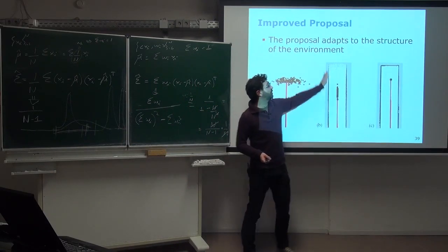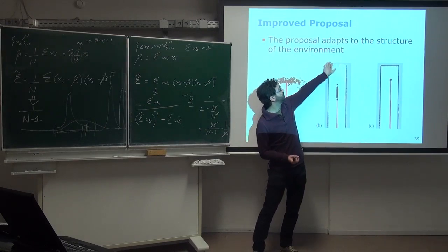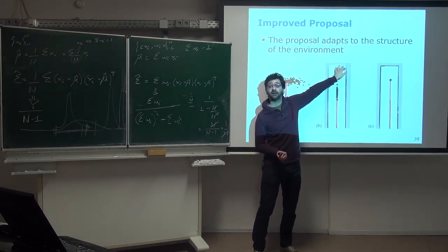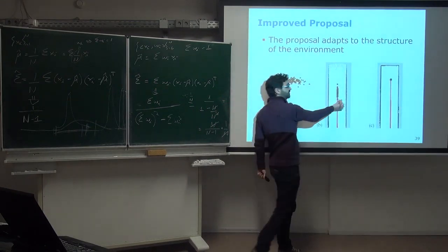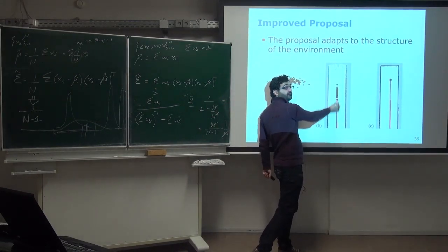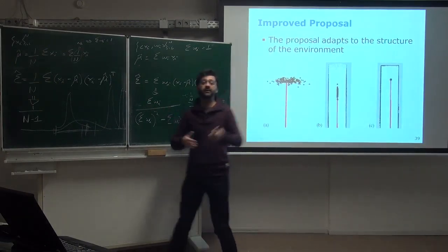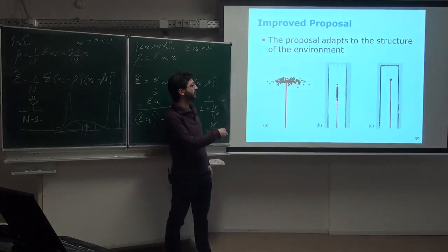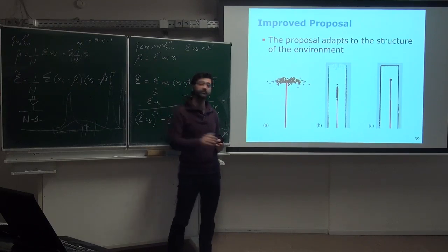If we have a long corridor where we basically are constrained on the left and on the right side, but there is no constraint on the top side, our likelihood will be much smaller here, so very, very tight here. But in this direction it will be very long because there is nothing that can constrain the laser in this direction. There is no wall here, no wall here, so it's free to go wherever it wants.